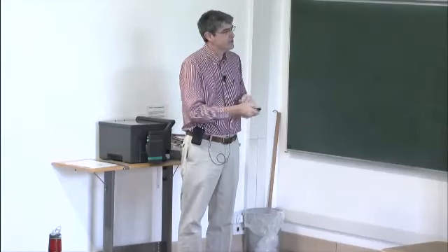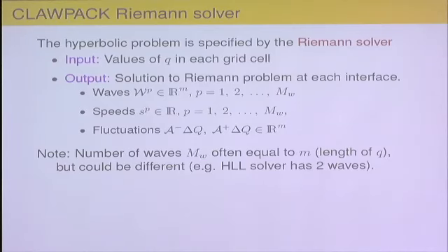So, for example, there's the HLL, Harten-Lax-van Leer approximate Riemann solver, where you always just use two waves to approximate the Riemann solution with a constant state in between. That could also be incorporated into this framework.